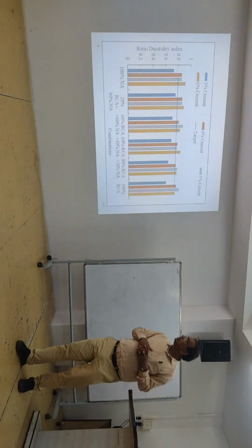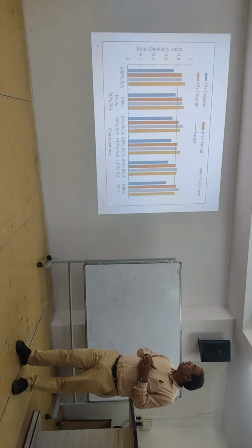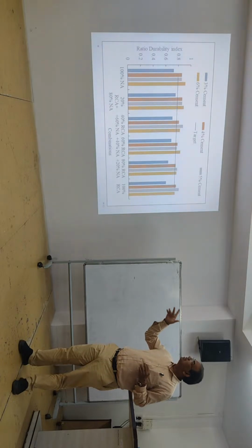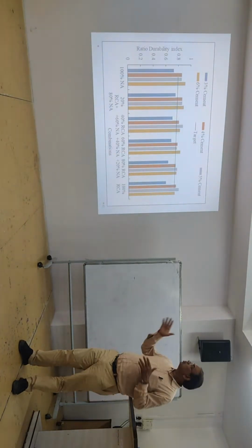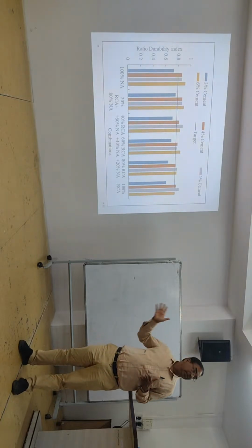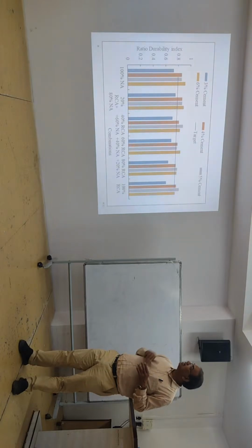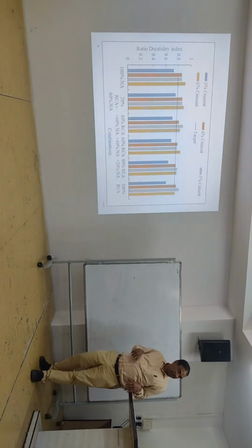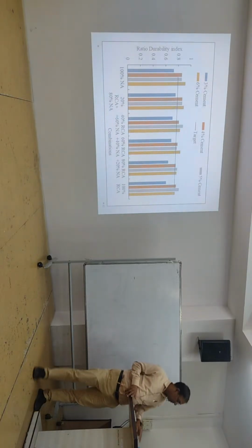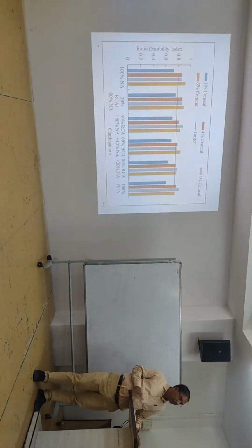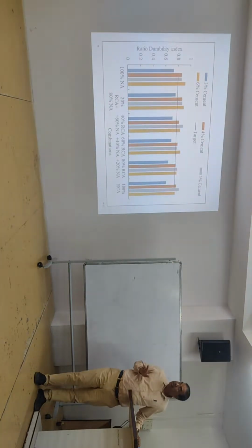Again, your durability you can see, almost 3%. You can even go with only 3% cement, which is commercially less. Even with 4% cement, we can use this 100% RCA, and that is sufficient for your target, your durability achievement. It is also achieving the durability test. So certainly this recycled aggregate can be used for different purposes. This is not for the main road like a highway, but certainly in village roads you can use this.